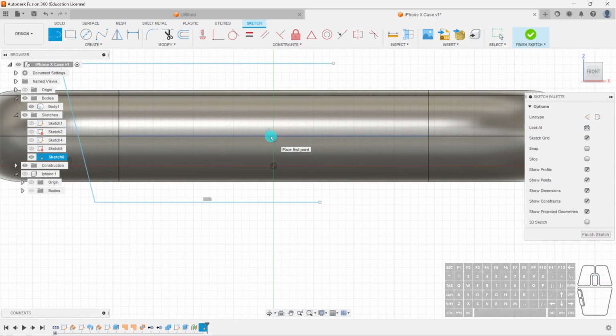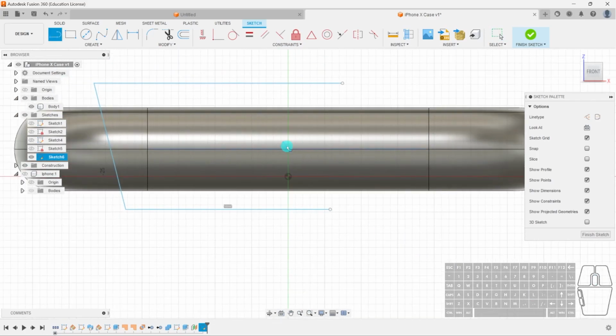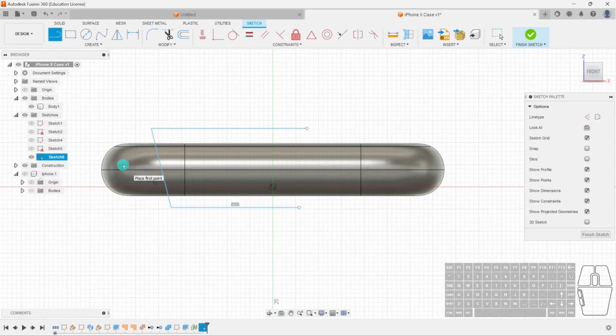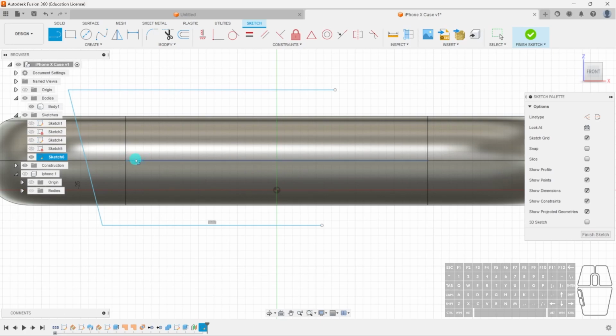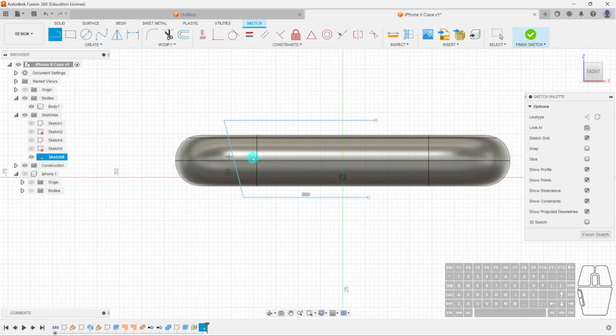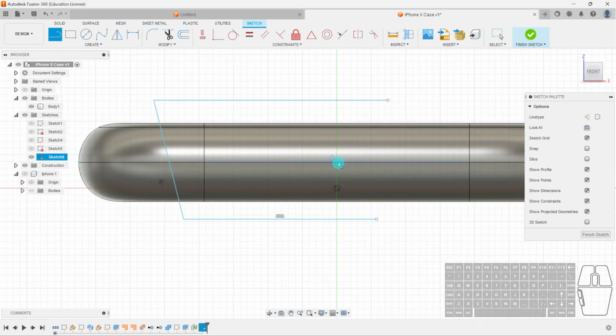So what I want to do now is to find my middle line, which in this case is the origin. So I know it's a line, but let's just say this was positioned off center from your origin. I know that this line is essentially the same distance away from the two sides. So my midpoint line here, I'm going to select it and I'll draw upwards, making sure this is a vertical, which it should be anyways because it's perpendicular, but just in case.